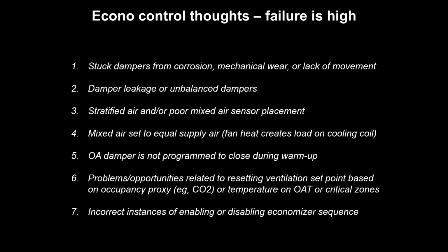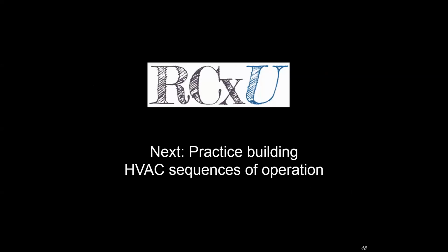As we've said a few times now, there are a lot of modes of failure associated with economizers. Some of it can be control related, some of it can be mechanical in nature, sometimes it's a combination, but this is a device that you're going to want to pay extra attention to in any type of recommissioning assessment environment. With that, we're going to move on to some of our other HVAC sequences of operations, such as duct static pressure reset, hydronic pump control, and some of the other reset variables that we could look at.